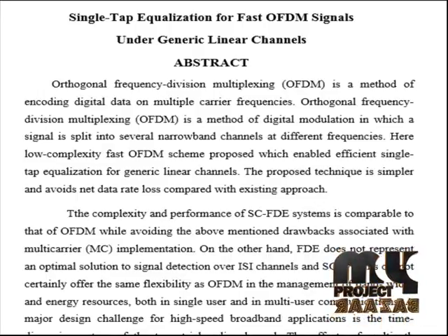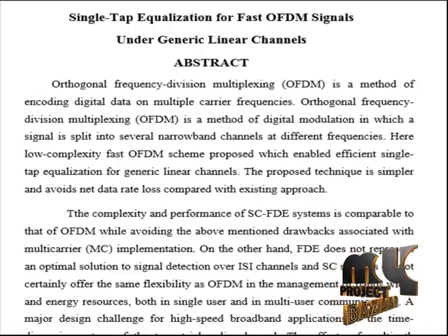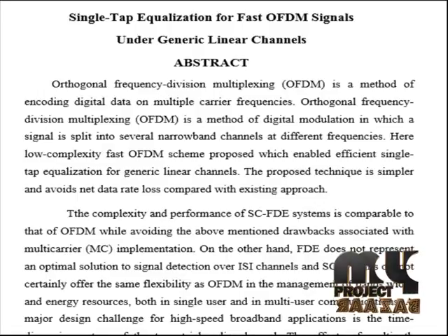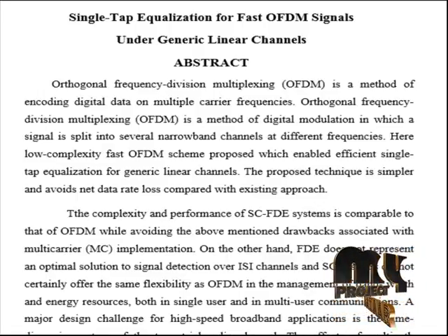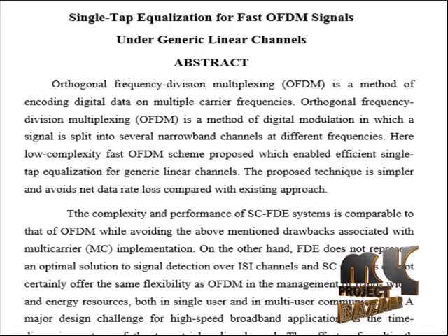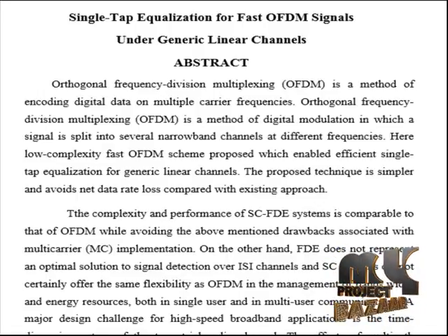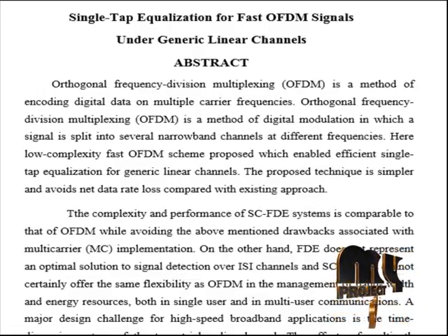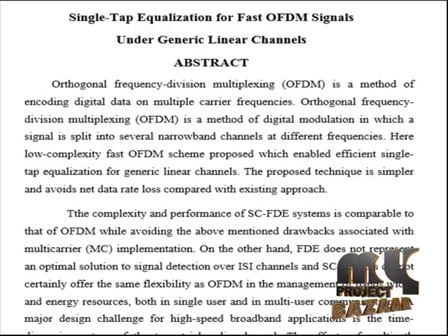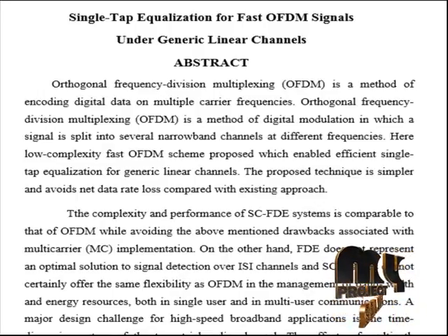The complexity and the performance of the SC-FDE system are comparable to those of OFDM while avoiding the above-mentioned drawbacks associated with multi-carrier implementation. On the other hand, FDE does not represent an optimal solution to signal detection over ISI channels, and SC systems certainly cannot offer the same flexibility as OFDM in the management of bandwidth and energy resources, both in single user and multi-user communication.